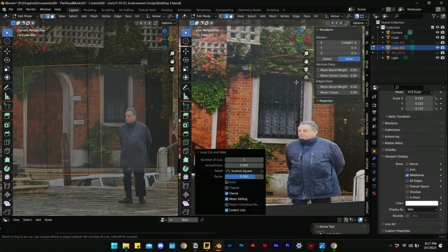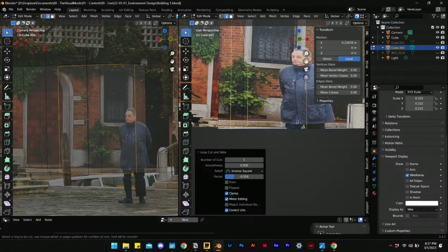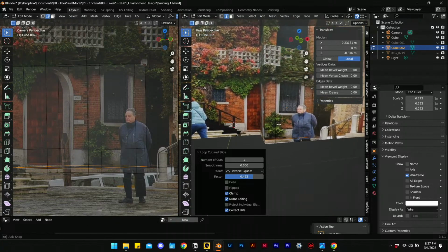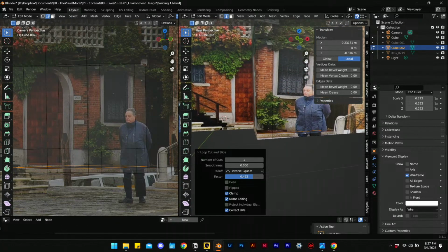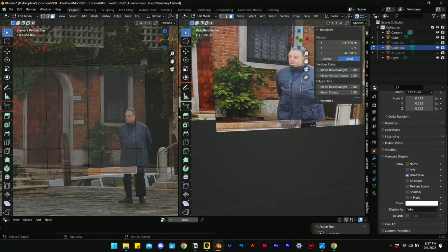You want to go in order of what the most important aspects are. It's actually the most important in terms of simplest and largest influence over the 3D object is this band right here. So I'll set up that band right there. We have the curb creeping in. So I do want actually a floor condition if these cubes are meeting anywhere near the floor. Now I can just start pushing things out. So I can select these faces down here. Extrude.